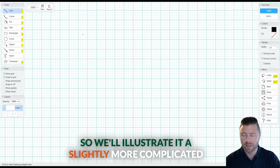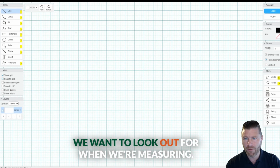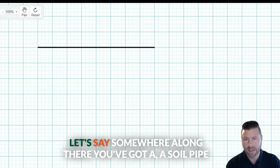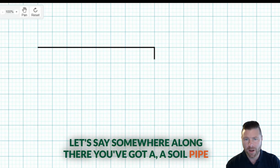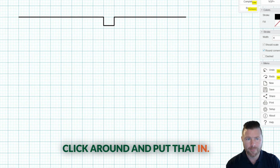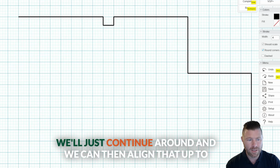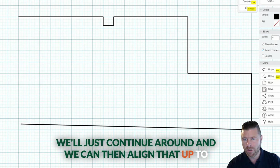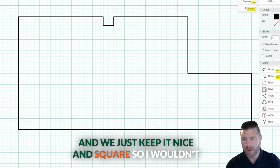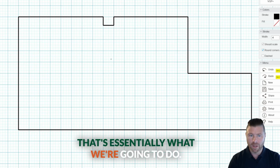So we'll illustrate a slightly more complicated room than a rectangle, just so you've got an idea of the kind of things we want to look out for when we're measuring. So if we use the line tool, we measure across, let's say somewhere along there you've got a soil pipe or something that's popping out of the wall. We can just click around and put that in. And let's say there's a section here that goes under the stairs. We'll just continue around and we can then line that up to roughly where that one finishes, and we just keep it nice and square. So I wouldn't start being too accurate about if this wall is off. That's essentially what we're going to do.